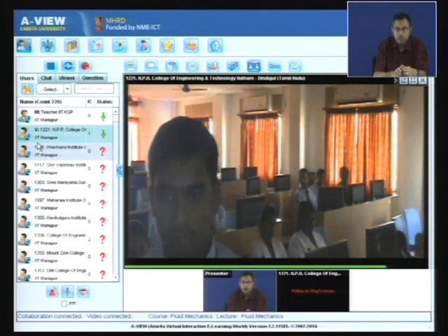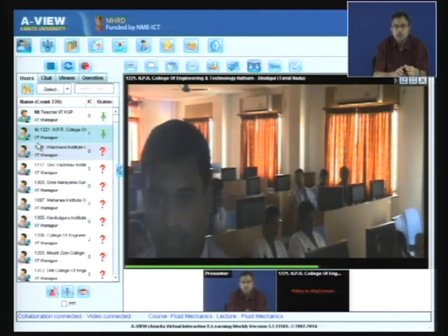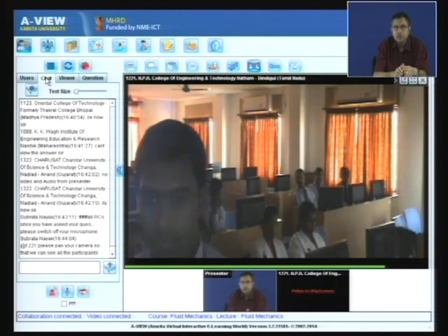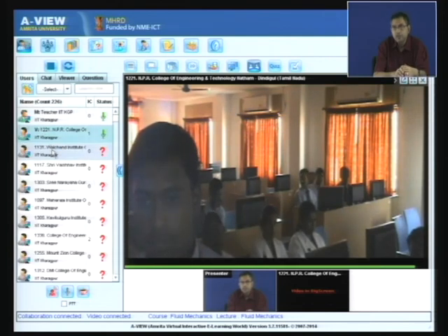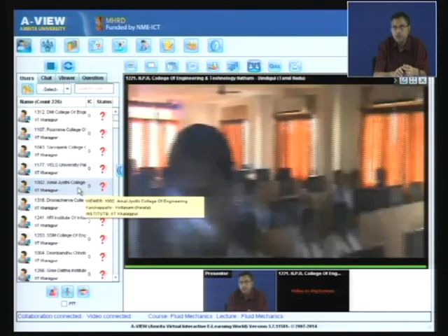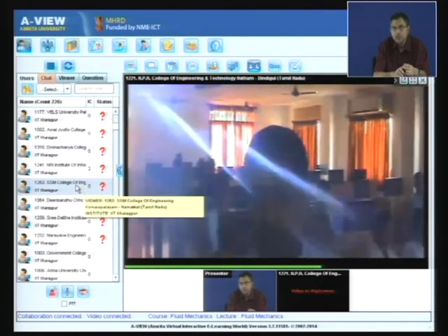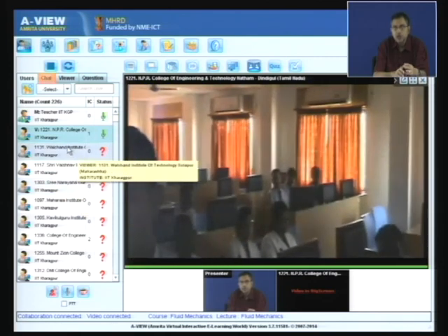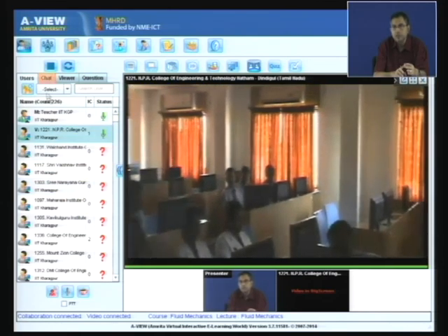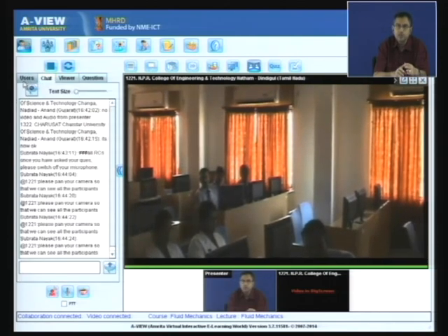When calculating the wall shear stress, you require information of the velocity profile, but even if you do not have the correct velocity profile, you can use integrals of the velocity profile to calculate the wall shear stress in an approximate sense. So, the momentum integral equation gives you an approximate yet very accurate method of calculating the wall shear stress without correct knowledge of the velocity profile, provided the boundary conditions are appropriately satisfied.